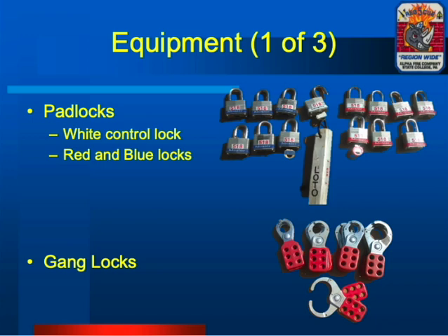So as I said before, the red and the blue locks are used alone, with or without locking devices. The keys, I said, will be placed in the lockout tagout toolbox and secured with the white lock to maintain a single point of control on all lockout devices.